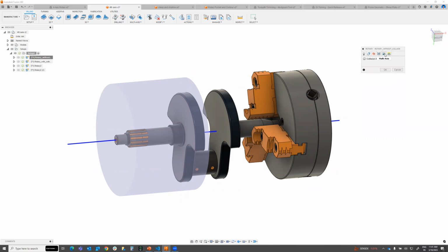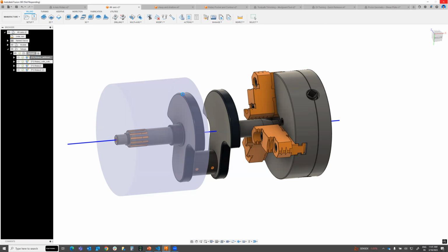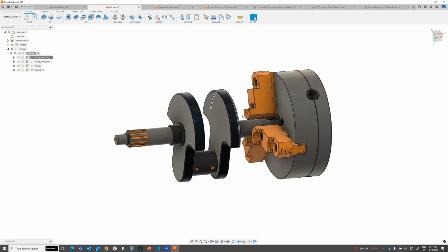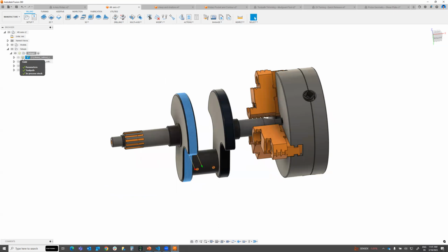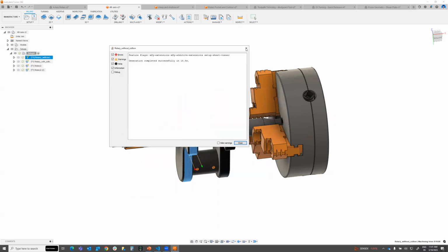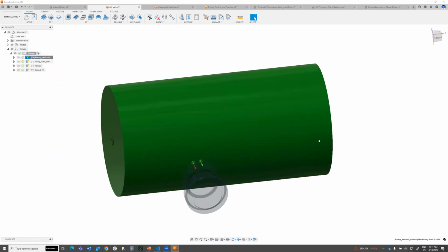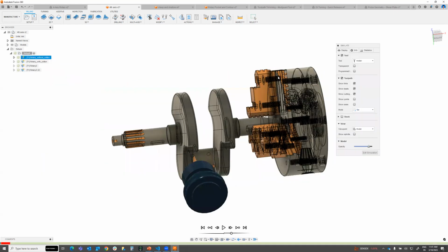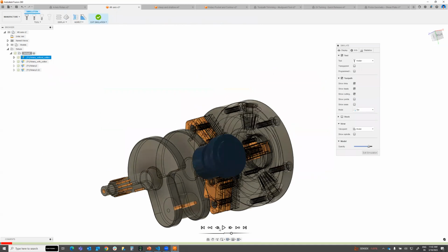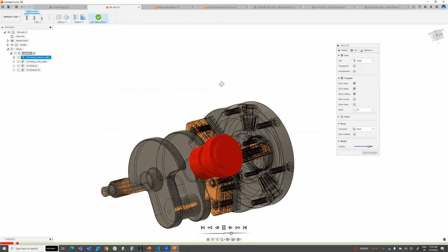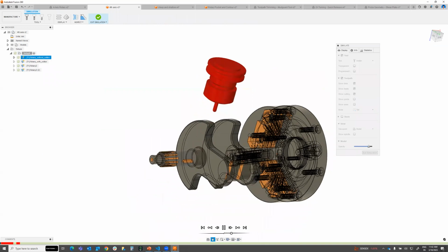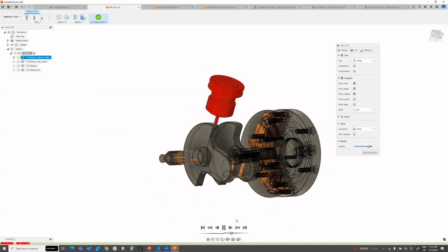Then here there are options. I will not use the automated collision options now. Let us see how this spiral toolpath is going to show. I will select this, and I can go here to simulate the toolpath. Right click, and you see the simulating of the toolpath. I will not use any stock options, and you can see now my toolpath is going to play here.